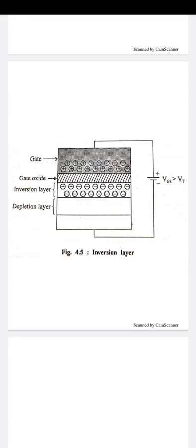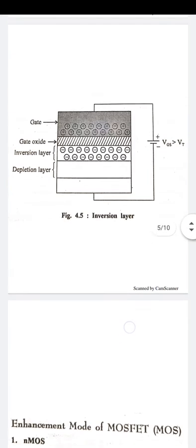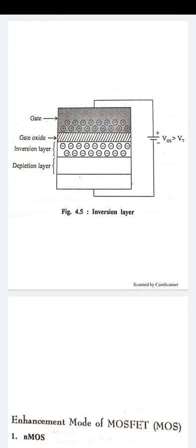So now if a voltage is applied between the drain and source, current flows through this induced n region, carried by the mobile electrons. The MOS device is in the conduction mode basically. So in the complete process it is very clear that the gate voltage is applied only to form the channel. So that is called the controlling voltage, and the value of the current flow between the source and drain depends upon the drain to source voltage.